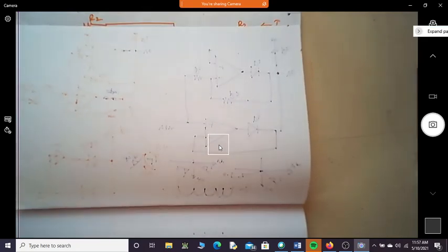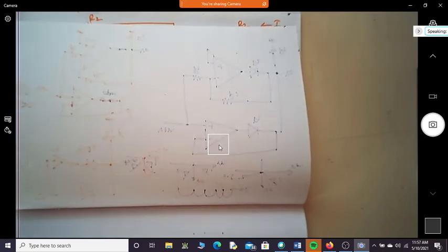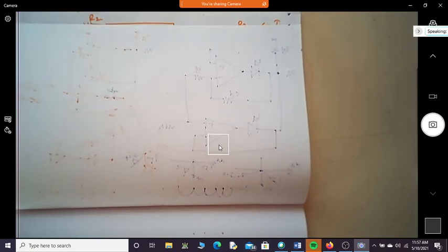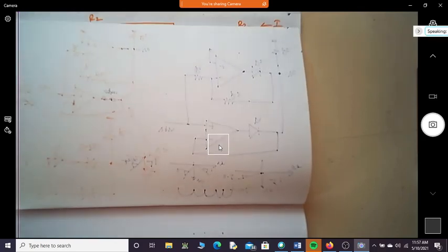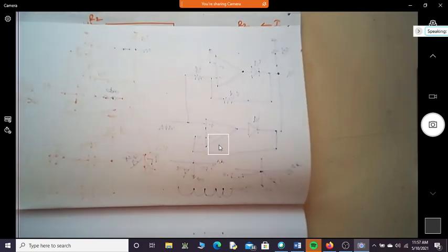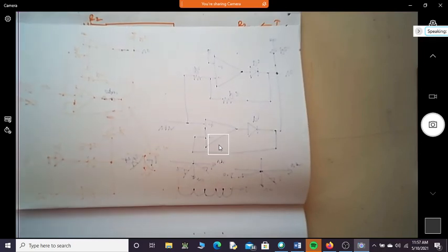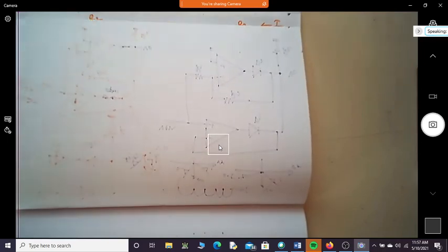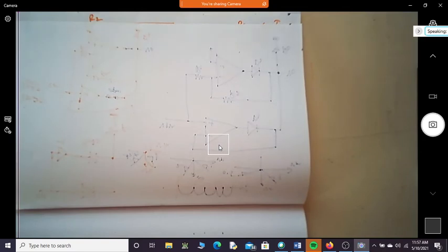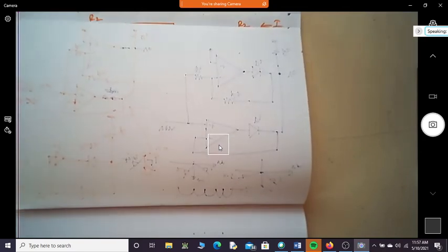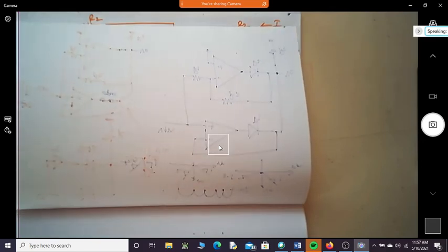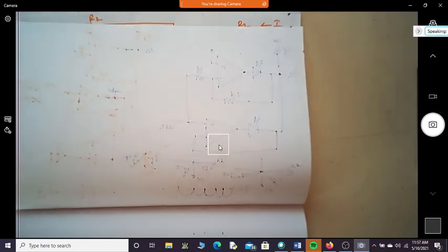In a PLL, we have a VCO, which may not be made using a 555 timer because a VCO can be realized by so many circuits. In that PLL, we don't have a 555 timer as the VCO. We have different circuitry there. But typically, if you apply a different DC voltage, it will run with a different frequency. I think we talked about free running frequency.